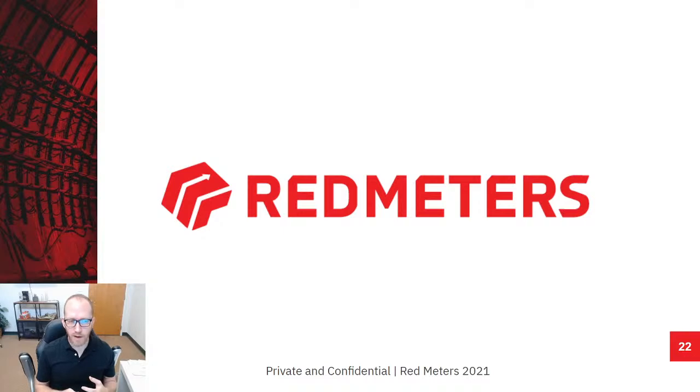Another common question we get is, the red meter has a liner, and the liner has a wear sensor, because the liner will eventually wear out over time. It could take as much as 3 years of running high velocity with abrasive slurries, nonstop 24/7. But eventually, it will wear down. And people want to know, how will I know when that wear sensor is triggered? Well, in Cinder, we created a persistent warning in the interface. So when the wear sensor's been broken, that persistent warning won't disappear until a new cartridge is installed.